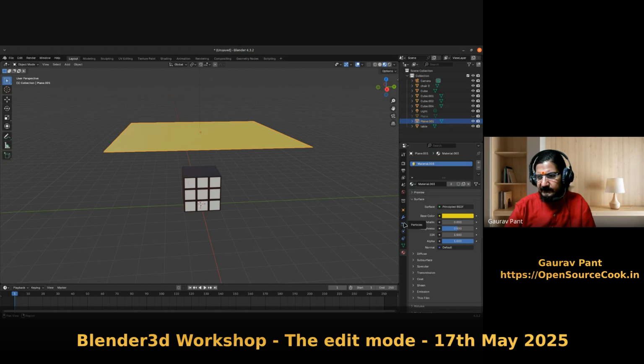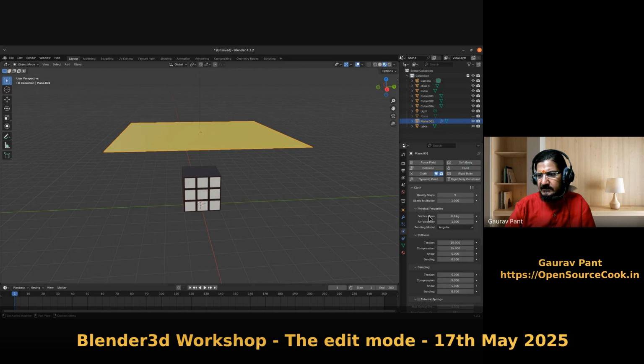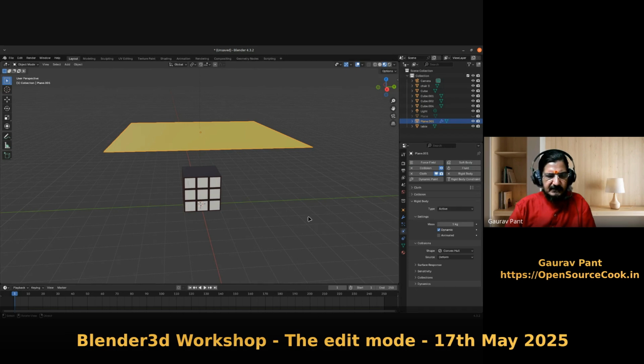We will go into the physics tab over here, and we will say it is cloth, and we will enable its collision. Fine. Also, we will make it a rigid body, and we will say it is active. Active means gravity will affect it. Gravity works on the Z axis, so it will fall from up to down, and you can decide the weight and all. Everything is there. This is quite interesting software. Fine. So we will just leave it like this.